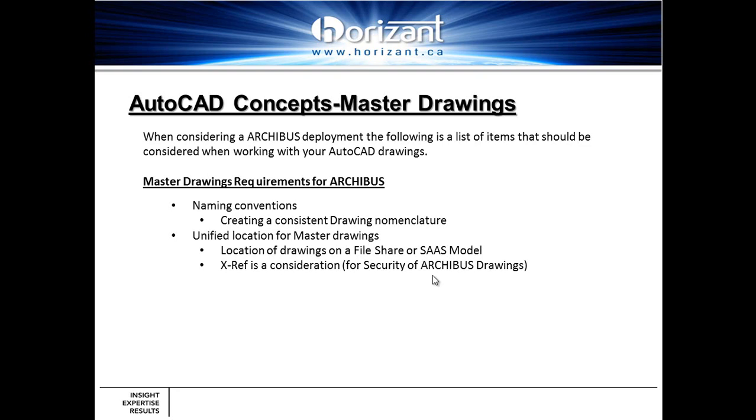The other aspect is do you consider XREFs or deal with a security model when dealing with your drawings? Who has access to these as-builts in this location? Do you break them out into different XREFs? You can take an XREF and break it out into a furniture drawing, an architectural drawing, and an ARCHIBUS aspects drawing, and combine those XREFs together.